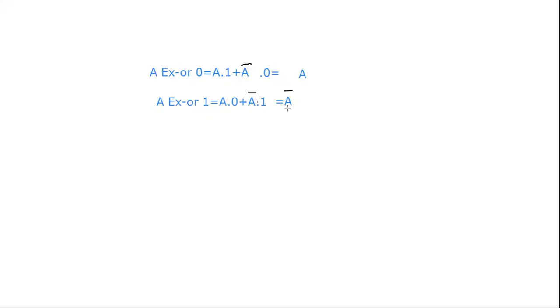So if you want to identify whether it is in the complemented form or the uncomplemented form, you need to connect the corresponding output of the OR gates with the exclusive OR gate, whether it is connected to 0 or 1, based on what type of output we are choosing. For example, if you choose the output in the complemented form, you have to connect A with 1, and if you want the direct form, you connect A with 0, whether it is F1 or F2. Okay.